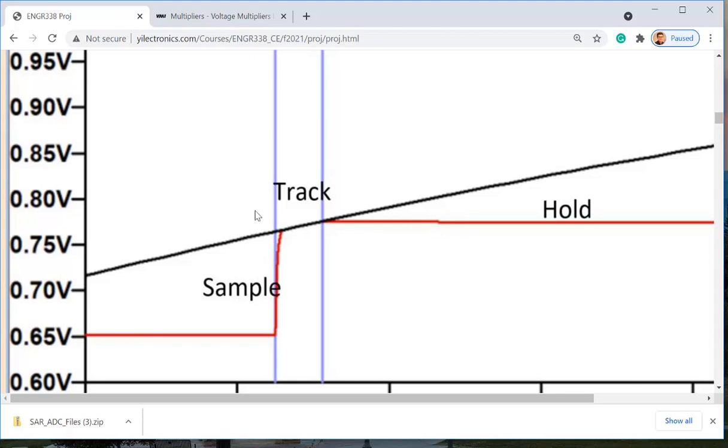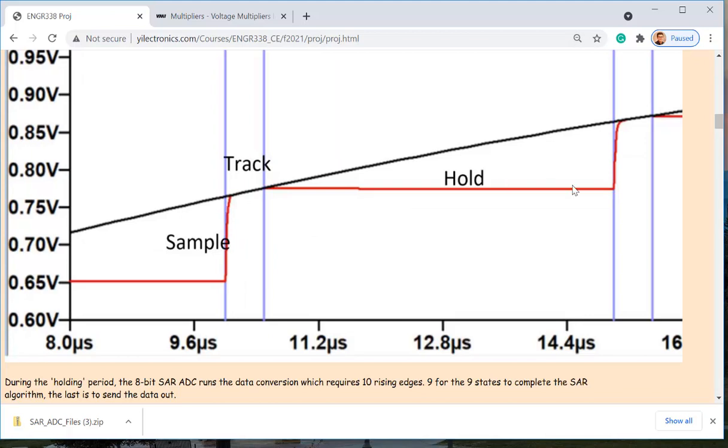So why do I want to hold it? Analog signals are continuous signals, like the sine wave. You can see the black line here, right? But you want to digitize it. What does that mean? You sample, boom, boom, boom. Sample it really frequently, and then you can recover the sine wave. But actually, you are losing points. Are you losing points? Yes. See all these points? All these parts of the sine wave are being lost. You're not sampling these at all, which is fine. You're not getting infinite resolution for any ADC.